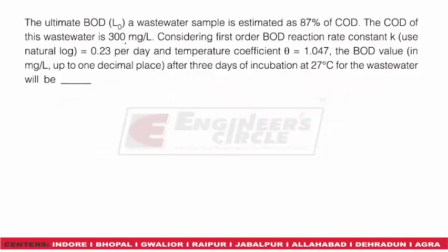The next question is, the ultimate BOD L0 of a wastewater sample is estimated as 87% of COD. The COD of this wastewater is 300 mg per liter. Considering first order BOD reaction rate constant K, use natural log equal to 0.23 per day and temperature coefficient theta 1.047. The BOD value after 3 days of incubation at 27 degrees Celsius for the wastewater will be.